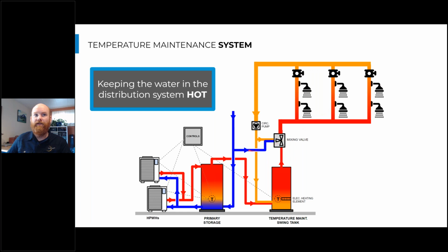And so we typically circulate the water with a hot water circulation pump to reduce the amount of wasted water we're flushing down the drain. And it's not just wasted cold water in that sense, it's wasted hot water because we've already heated this water, we've lost temperature of that water, and now we're going to drain it. And so it's part of that hot water load. And so it is a significant amount of energy. So with a circulation pump, we can just circulate that water through that distribution network. And that keeps it close to 110, 120 degrees, depending on where you are in this circuit.